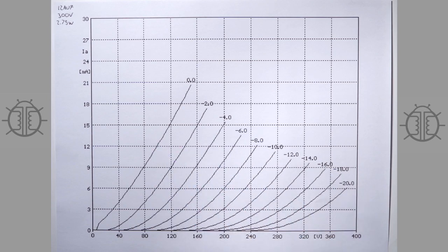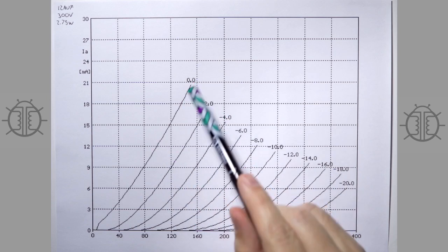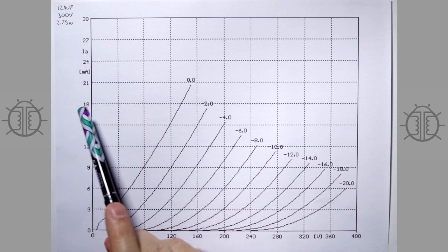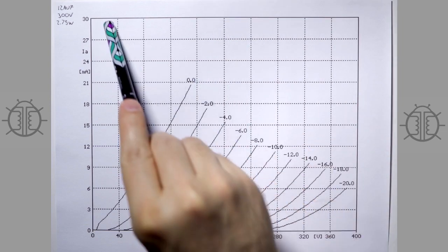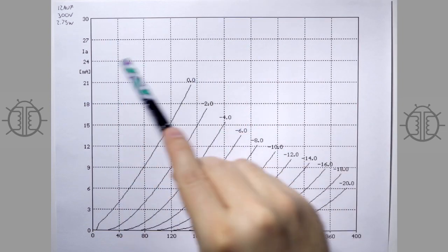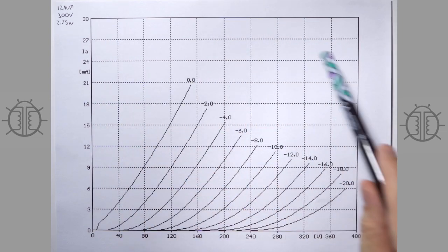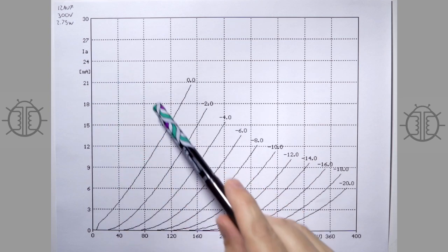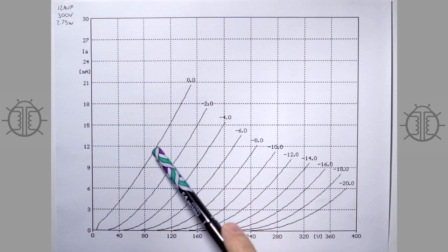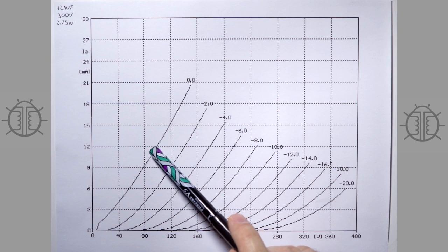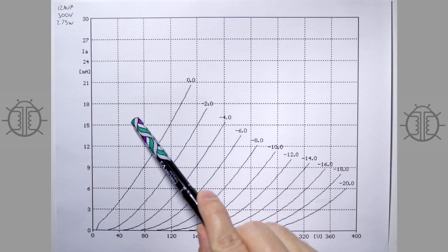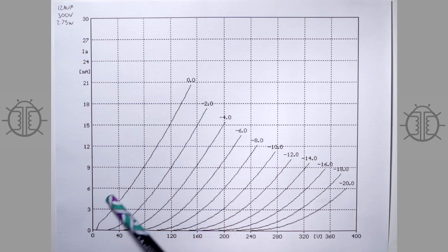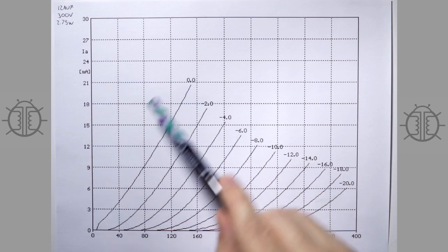And so another thing you should notice is that there's voltages and currents here, and you can see there's like a large area up here that's unused, and over here that's unused. These are areas that the tube cannot operate in. Over here it cannot operate there because it can't swing positive. The grid cannot swing positive of the cathode very easily, and when it does, the grid will conduct and heat up and potentially damage the tube.